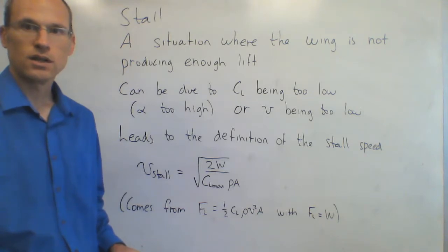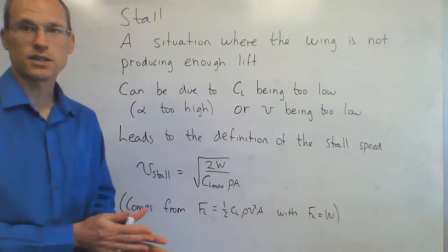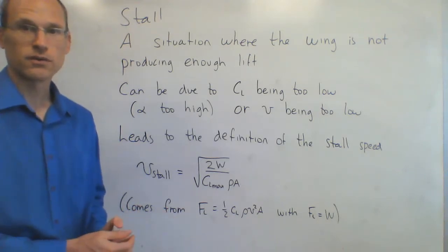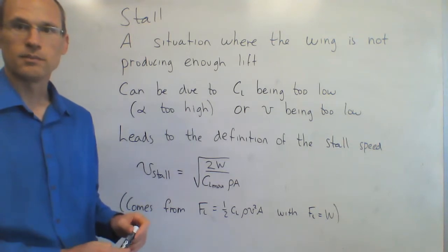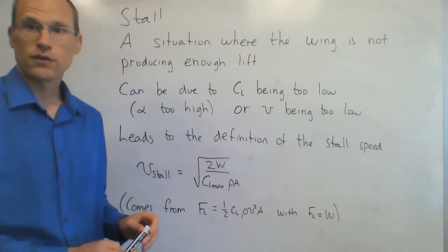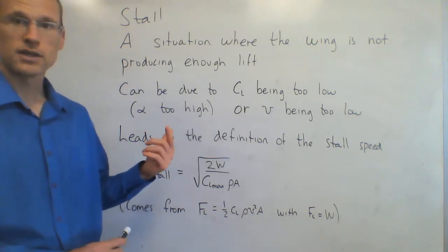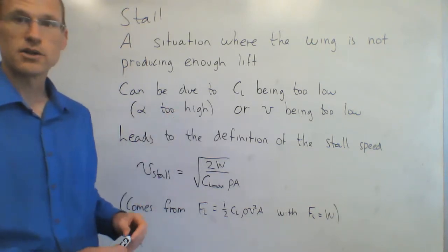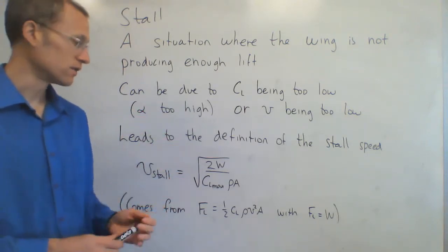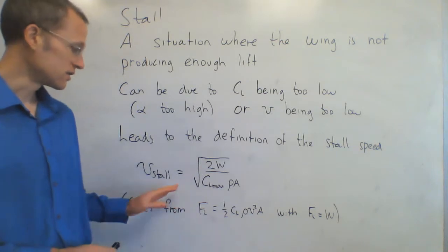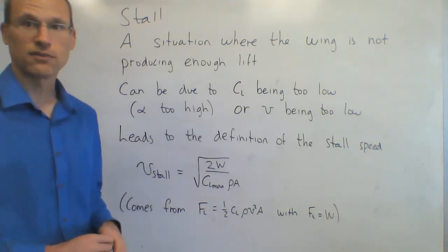You're going to be seeing some curves in a little bit, so you can obviously see where the CL max happens for some of those. It's basically the alpha that gives you the biggest lift coefficient. So we're going to see that as you increase alpha, lift gets higher and higher, but then this boundary layer separation happens that we saw, and so it starts to decrease, and so wherever that maximum value is, that's generally what we have. So that's the slowest possible speed you could possibly go and still produce enough lift to keep flying.